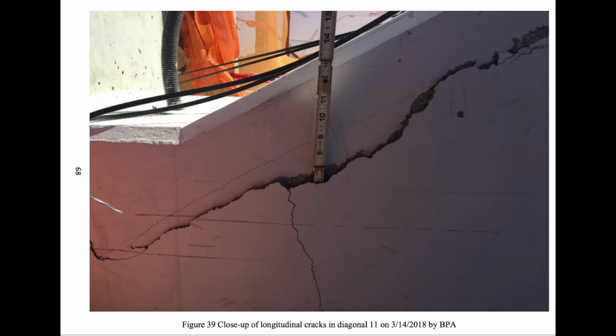And then remember, this is sliding. It's not the same as my shear going out to the side. They still had vertical uprights in here. They do have to go through those vertical uprights. And I'm not sure if there are any stirrups in this location down here. But with mine, the vertical uprights are irrelevant. They're in line with the shear path, so they do not cross it. So they're actually not an issue. My system of failure works.